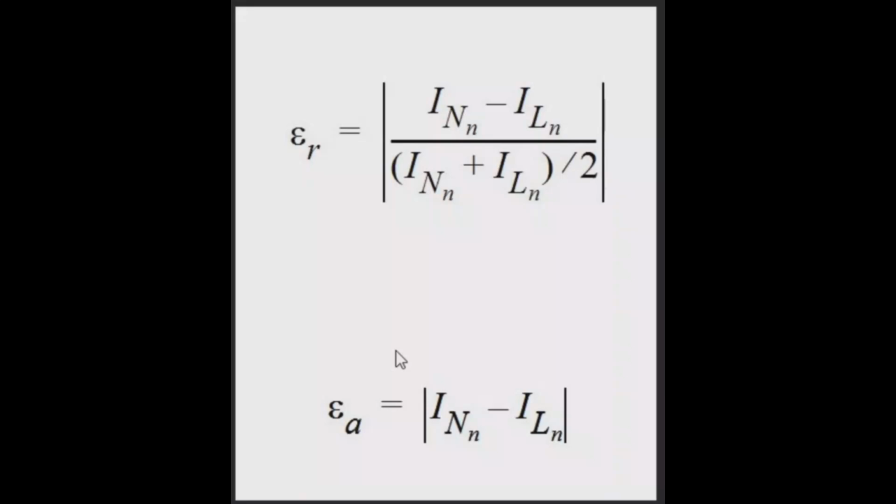We've solved the problem. And you can set these up in Microwave Office, and you have to set them up in Microwave Office. You have to come up with some reasonable estimates for these things, or else you will end up with either a problem that gives you the wrong solution, or you'll end up with something that never converges.